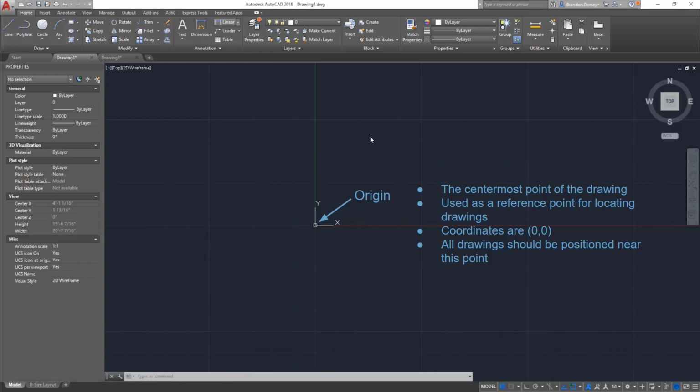Believe it or not, it's really easy to sort of lose track of where your drawing is and get way far out here. So the bounds of this space that you're seeing right now, like I said previously, these go to infinity. And sometimes you can just get way lost outside of them and you can lose track of your drawing. So using a command like zoom to origin, you can easily return to the very center point of your drawing and locate where your actual drawing is inside of this space.